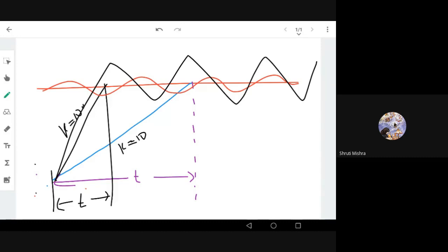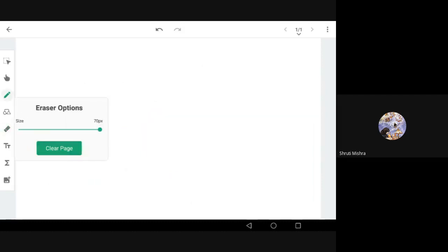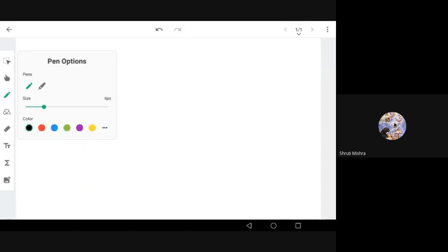So in order to reduce all those problems, we need to improve the controller a bit more intelligently. So why can't we have a controller which works on the error, and based on the residual error it should act? That means if there is a huge error, instead of the difference in error, you should check the area of error, how much area. That means integration.